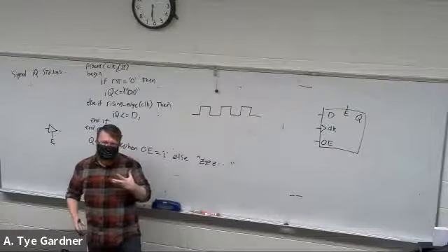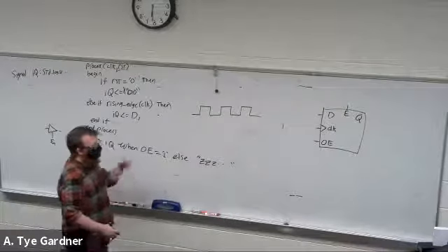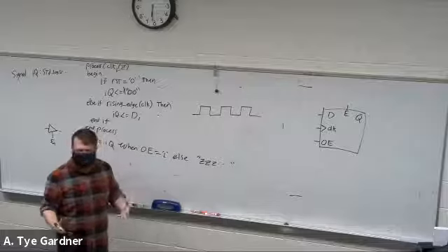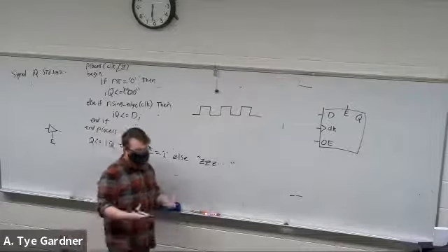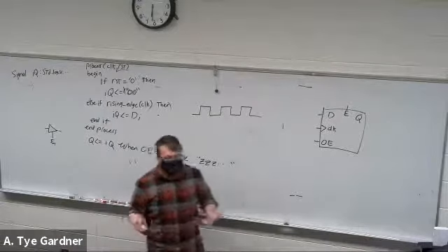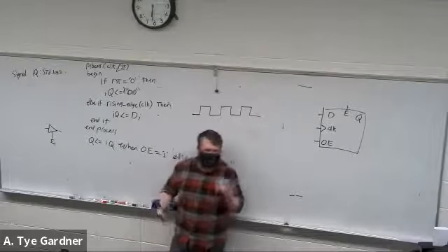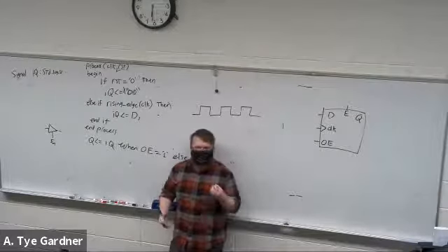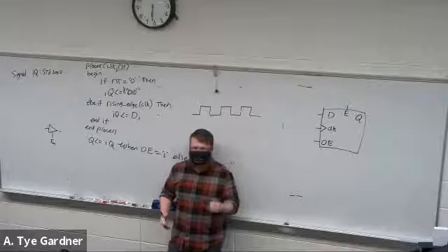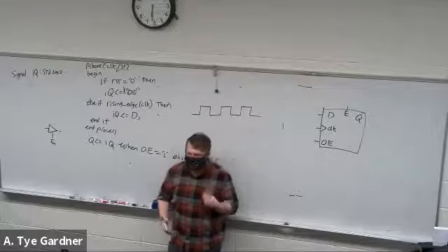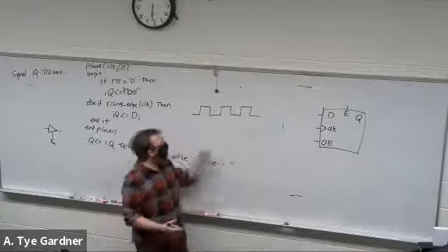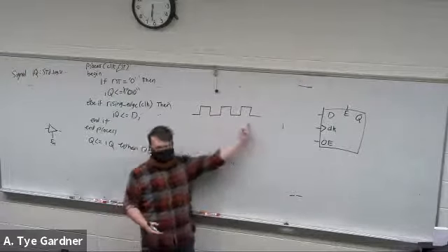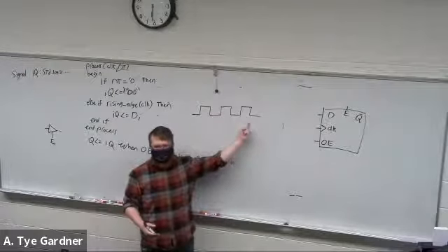So we make a clock on an FPGA, like what we're going to deal with later in this class, and a lot in 3610, using a crystal oscillator. So we literally use a crystal, and it generates a fixed frequency for us. So frequency is just a description of how often the clock happens.